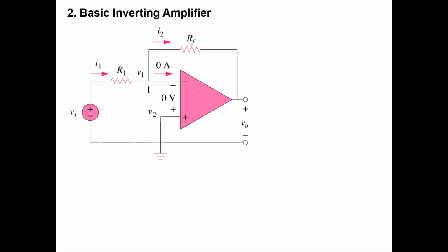So we have the negative feedback and all that, the assumptions that we make, these are the assumptions. Well, do you see negative feedback on this? Is there a wire going from the output terminal to the minus terminal of the op amp, or maybe not a bare wire, but a pathway? Is there an electrical connection? You see this connection right here. This is your negative feedback path. If that's not there, you don't have negative feedback, and then the VN and the VP can diverge. They don't have to be the same anymore.